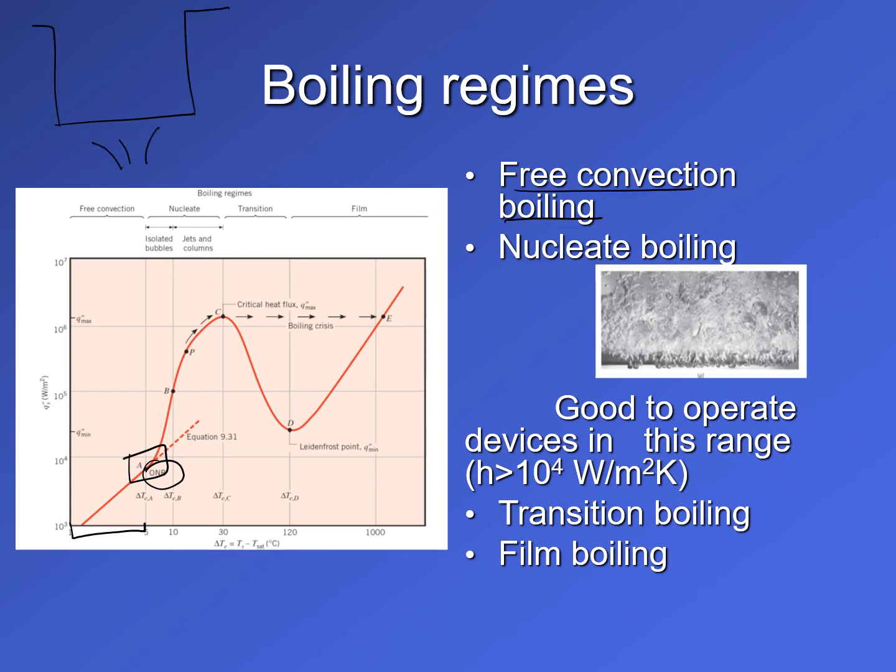which is heated from the flame below. You see some sort of recirculation in the liquid. Okay, so as the cold liquid gets pulled in and the hot liquid rises up because of these bubble nuclei moving up, this results in an increased rate of heat transfer, and that is what you see between points A and B.